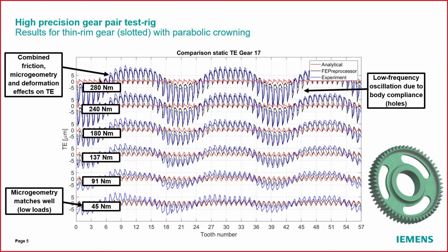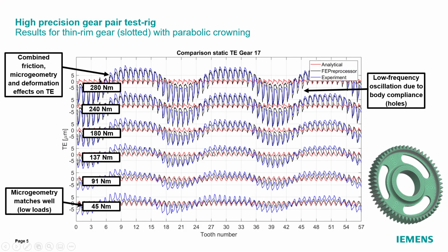And what we found is with the pure analytical approach, the older methods, with this heavily slotted gear, it doesn't take into account the variation of tooth stiffness, and you can see versus the experimental data that we measured, the blue curve, we're not getting that great. We're kind of getting okay correlation, maybe at lower torques, but as we increase the torque load and we look at the transmission error, we are not getting good correlation with the real world.